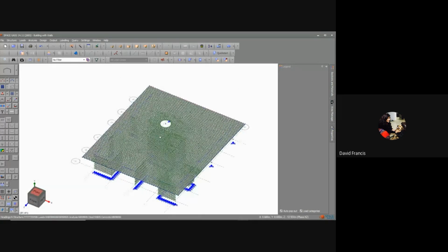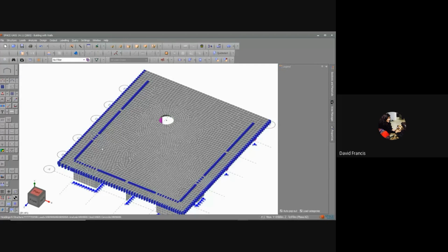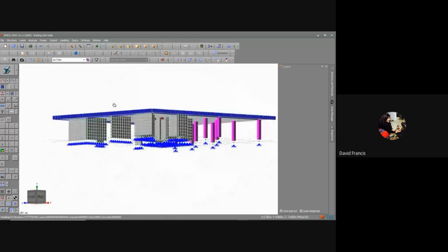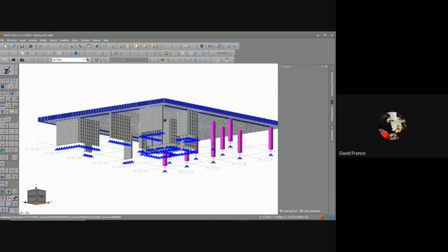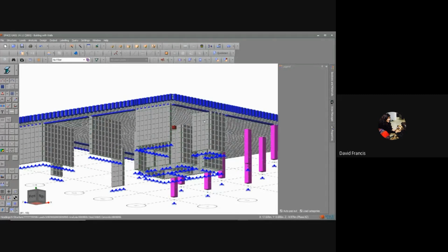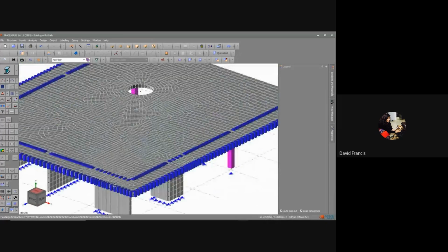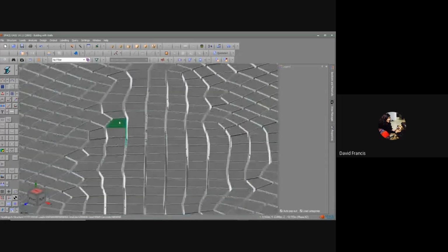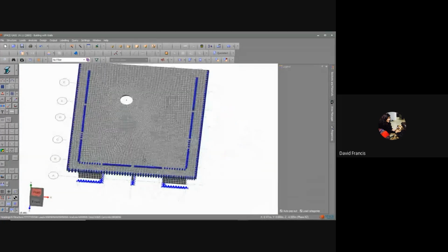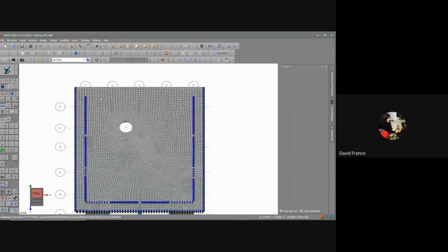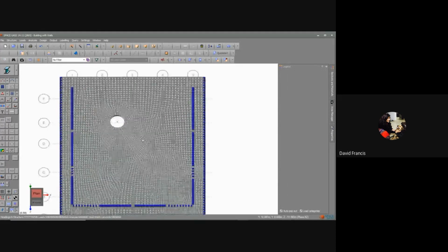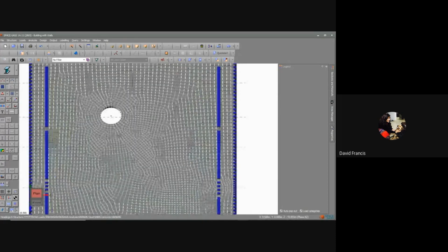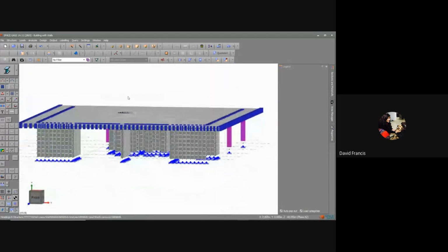And there is my mesh. If I go back to rendered mode, you can see what it's done. The hard line was defined only for that wall, so you can see how it's meshed in at that point. It's meshed the member as well. I didn't define it for the others. And where the hard nodes were, you can see the spacing here, particularly in there. It's bigger, and I had a couple down here as well. So where you want it finer, you can play around with those controls. That is one of the other tools as well.